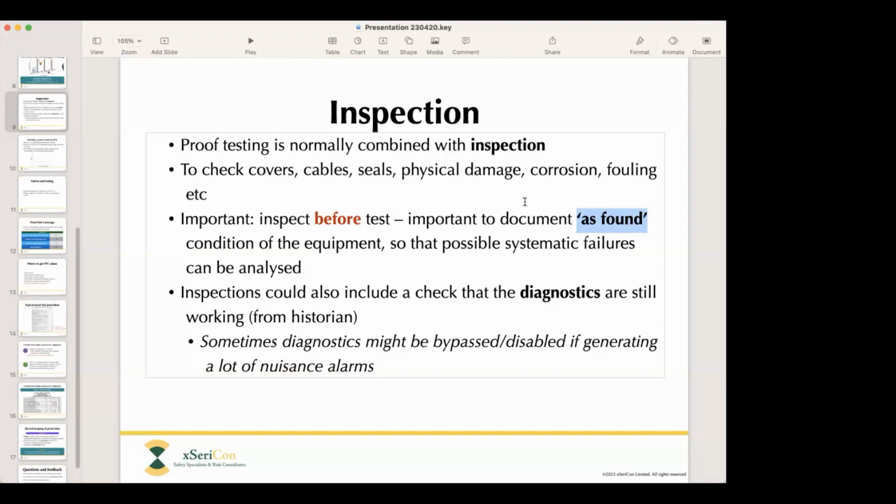That's important because if we find that the systematic failures are occurring at an unacceptably high rate, which means significant relative to the rate of the random hardware failures, the wear and tear rate of failure, then we need to be asking questions about how good our controls are in our inspections and whether we've made some unwarranted assumptions about the availability or the performance of the safety function during the analysis phase.